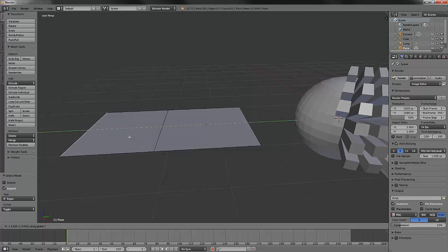And since we're here, here's a new one I'd like to show you. You're used to using X, Y, and Z to lock an axis. But instead of hitting Y, now I'm going to hit Shift and then X. As you can see, now I can extrude along the Y and Z axis simultaneously while keeping the X axis locked out. Being able to use multiple axes at once can be very, very handy. So remember that shift key. Shift and the axis you don't want.